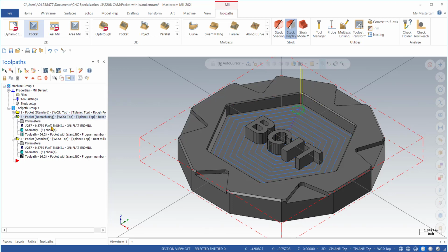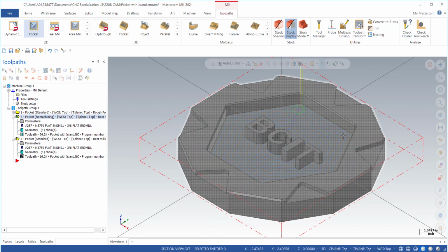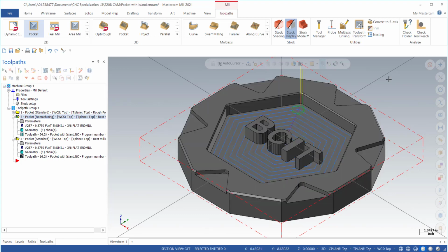So now you can see where the spiral is. The tool went down negative 0.6 and then it created a spiral, went to 3/4 D. So now the pocket is finished to depth. Now the only thing left is to clean the walls.